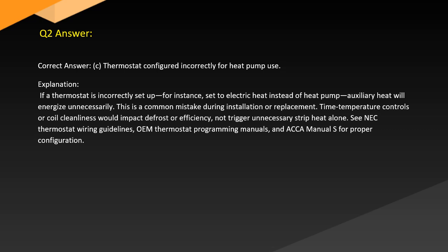Answer. Correct answer, C. Thermostat configured incorrectly for heat pump use. Explanation. If a thermostat is incorrectly set up, for instance set to electric heat instead of heat pump, auxiliary heat will energize unnecessarily. This is a common mistake during installation or replacement. Time temperature controls or coil cleanliness would impact defrost or efficiency, not trigger unnecessary strip heat alone. See thermostat wiring guidelines, thermostat programming manuals, and ACCA Manual S for proper configuration.